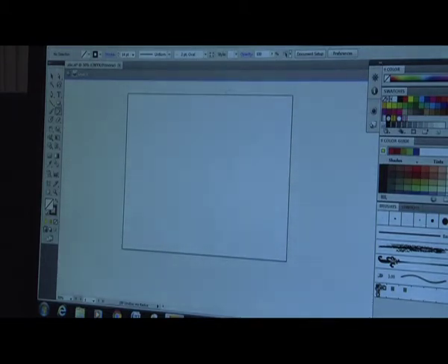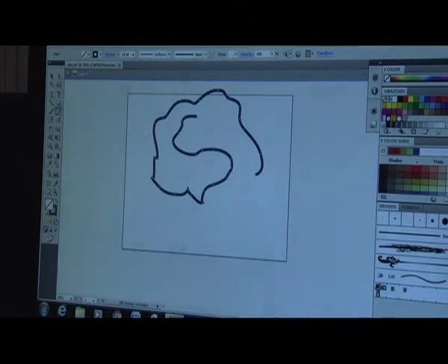Draw another line, this time as you loop back to the starting point. Hold Alt/Option as your pencil tool reaches the start point. A circle icon will appear next to the pencil tool to indicate path closure.